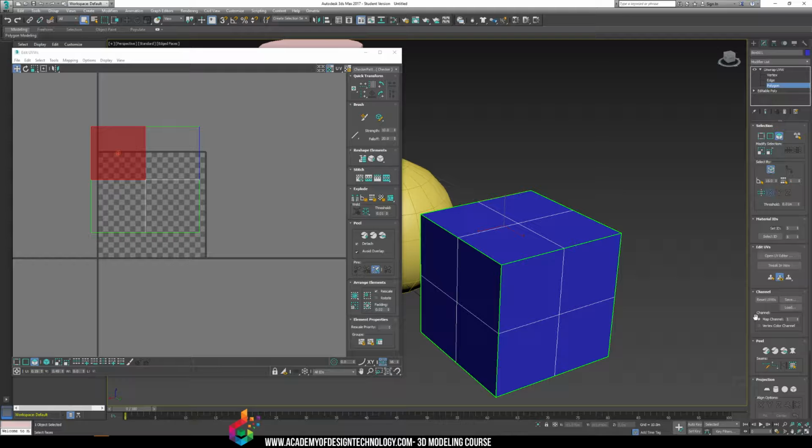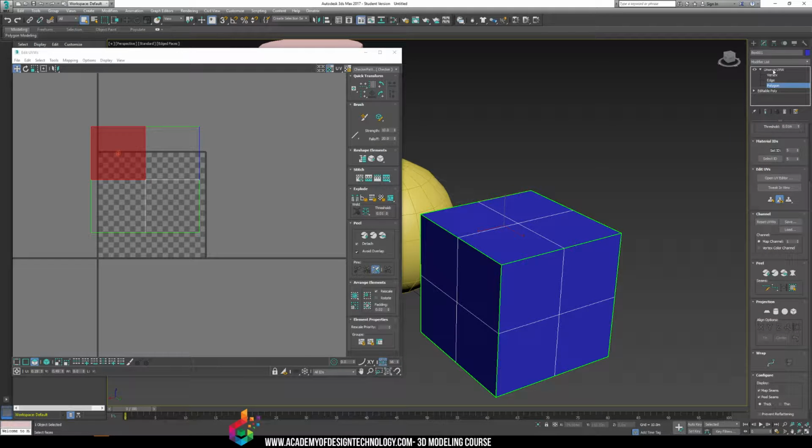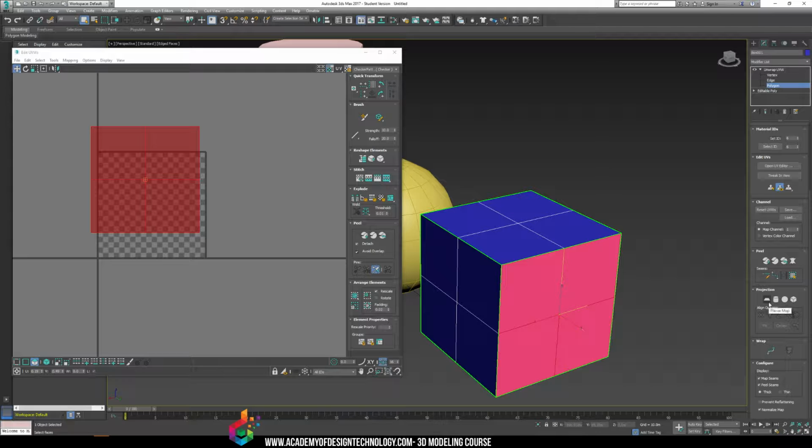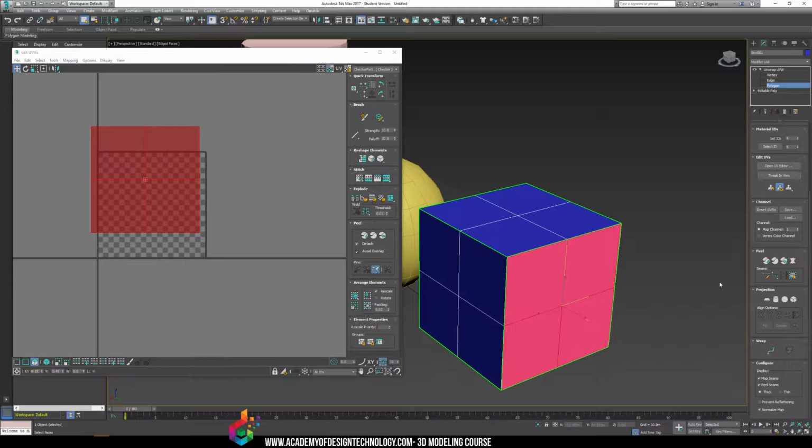And if we go down our list inside the 3D space here, we have our edit UV, unwrap UV polygon stuff. We have a thing called projection mapping. Now, what projection mapping is telling 3D Studio Max is that whatever polygons you have selected, when you click on one of these options, you're telling a special camera to look at the model from that perspective, like from a flat perspective, from a cylindrical perspective, from a spherical or box, so that it lays it out inside our scene here.